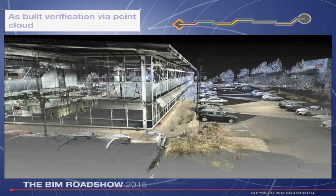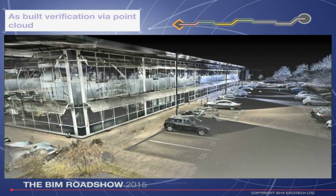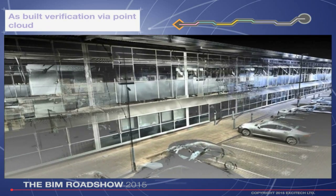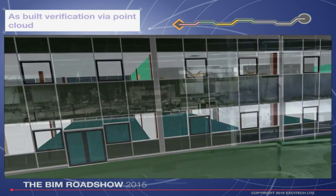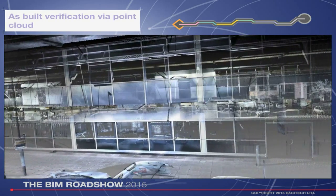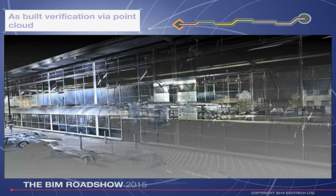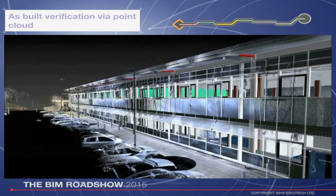So that image I showed you before of the beam, it's just using Navisworks. It's reading the data that we're getting in from the point cloud with the model that should now be as built, and just simply walking around it and ensuring that the data in both environments are LOD 500 as built, and I can now provide with confidence a true as built delivery as required.